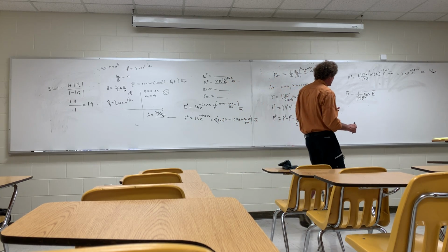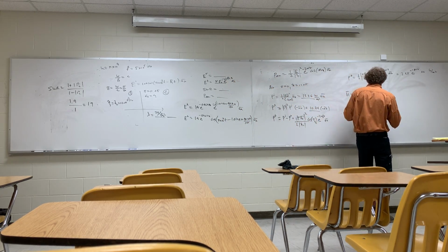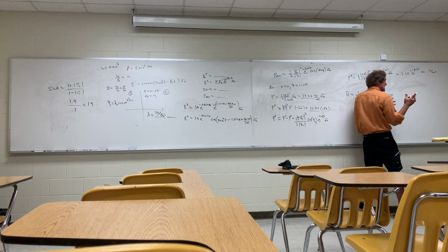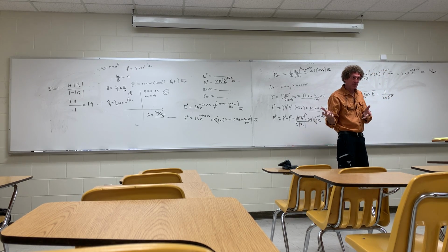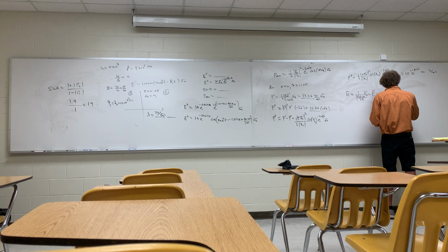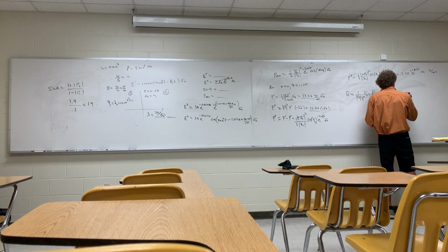So let's go over here and let's do it in the phasor domain. First, eta 2 was 1 over, I'm going to just say it was 28 about, and the angle here was e to the j, I'm going to say it's about 45 degrees. It was actually 43 something, right? We'll leave it like that. Unit vector in direction of propagation is AZ, right? Crossed into the E field.